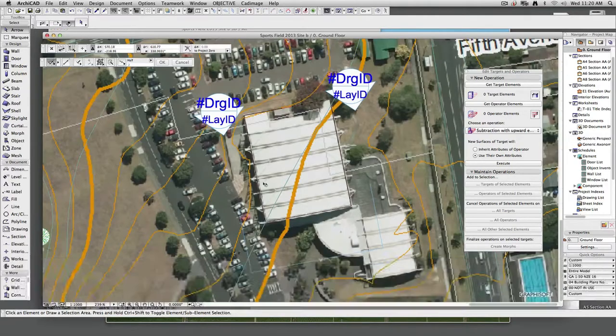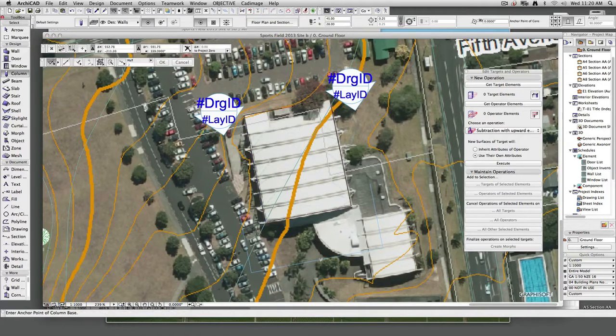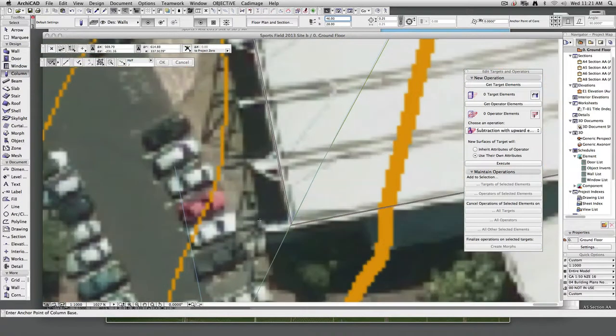All right. If you want to do the columns and stuff around the side, you can do that. I'm not too worried. It does prove that you can use ArchiCAD's column tool. Again, I'm going to set the base to 28 and the top to 46 meters because I know that's how high my building is. I'm going to pop one. Let's just zoom in here a bit.